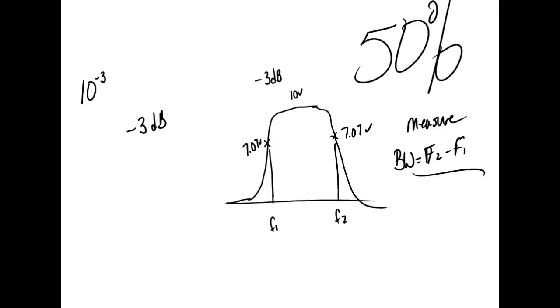It's just like when we measure VB. If I don't know what VB is supposed to be, then making measurements is nothing, not unless it's operating perfect. If you got an amplifier that's operating perfect, and you measure those biases, then they mean something. If you got an amplifier that's not working and you don't know what they're supposed to be, and you measure those biases, it don't mean anything, right?